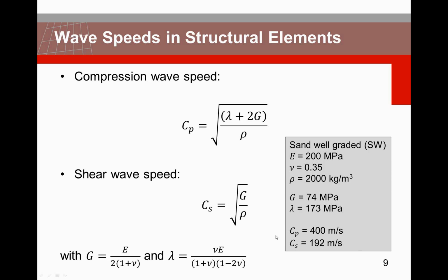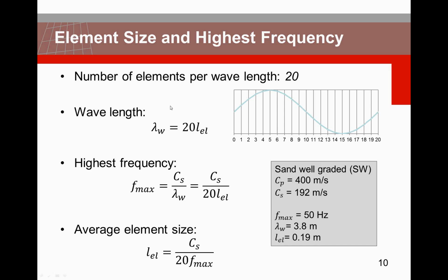This information we will use to learn something about an appropriate element size. Note that these are just an example for well-graded sand. In your model, of course, it's necessary to calculate it for your appropriate materials. How this is related to the element size.